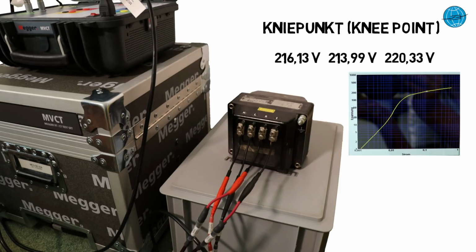representation. We could not determine the accuracy limit factor ALF with the MVCT. We searched the entire manual and all device options afterwards. On request, we were informed that the MVCT can be used to determine the accuracy limit factor, but only within the scope of the test for the identification of the nameplate.